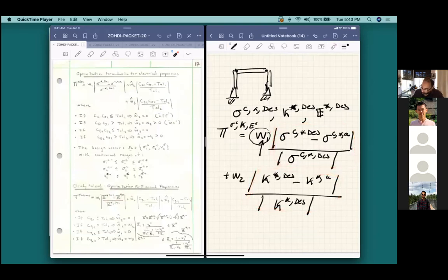Now, there's one other field that we would like, and that's basically also the elastic fields. So we take then basically the norm of the desired effective elasticity. So be careful, that's a tensor. So I'm going to put two lines underneath here to indicate that this is not just simply an absolute value. I take the difference between that and the effective properties that I have an approximation for, which again are given by those formulas, which you're going to derive as part of your homework assignment. And then I also have the elasticity of the desired properties here, and I take those norms as well.